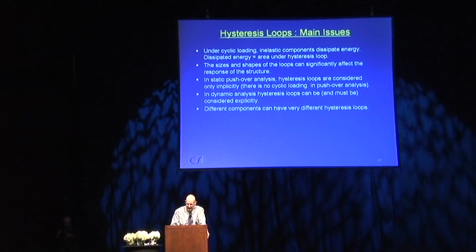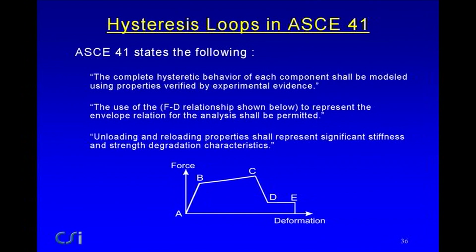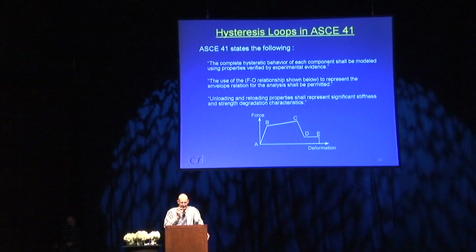In static pushover analysis, you don't consider hysteresis loops. They're considered only implicitly. But in dynamic analysis, they can be and must be considered explicitly. And different components can have different hysteresis loops. These are the major issues. What ASCE 41 says is the following: the complete hysteretic behavior of each component should be modeled. And the use of the force-deformation relationship shown below shall be permitted. And unloading and reloading shall represent significant strength and stiffness degradation character. You can read better than I can.